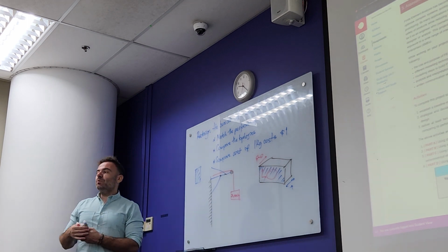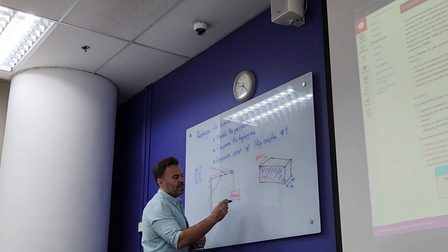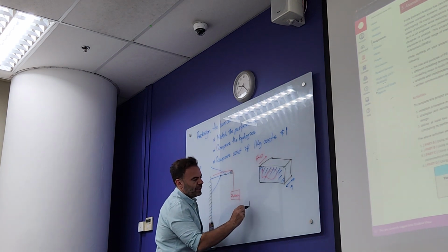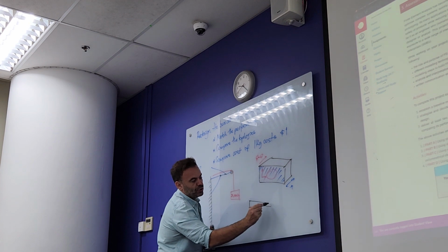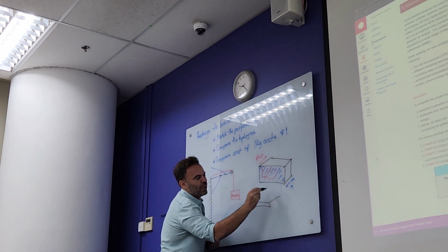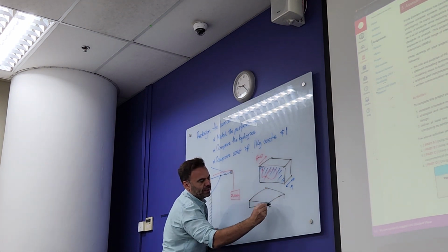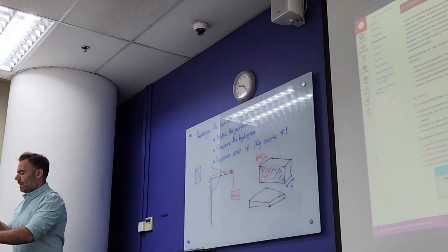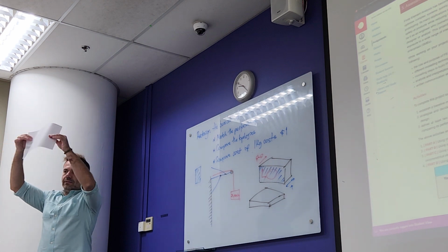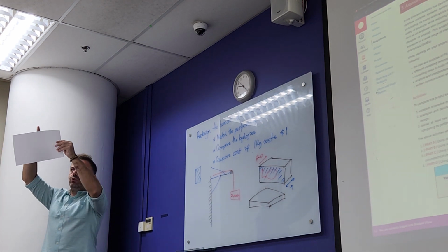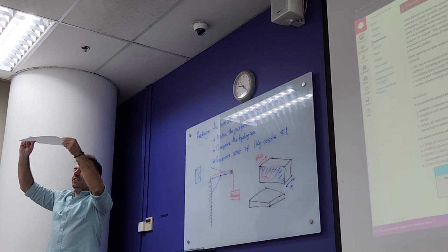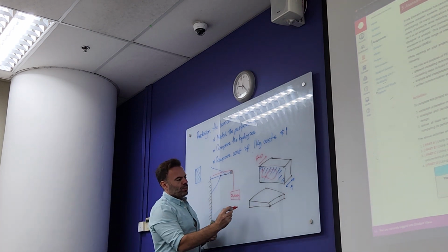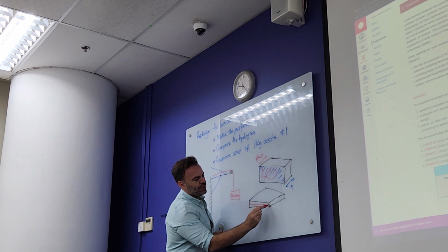Now when we're dealing with a 3D shell, if you have a solid that is thin, that's got 1 dimension much smaller than the other 2, like this, this is a perfect example. That's a shell. Yeah? 2 dimensions much bigger than thickness. Commonly, we model the middle surface.